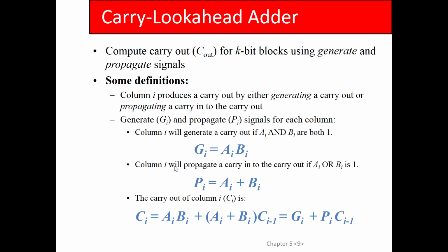So an approach for doing that is the carry-lookahead adder, where instead of waiting for signals to propagate through the previous columns, meaning the less significant columns, I'll just look at all the inputs and look ahead, calculating what my carry in is going to be if I had let it come through all the other full adders. Does that make sense?